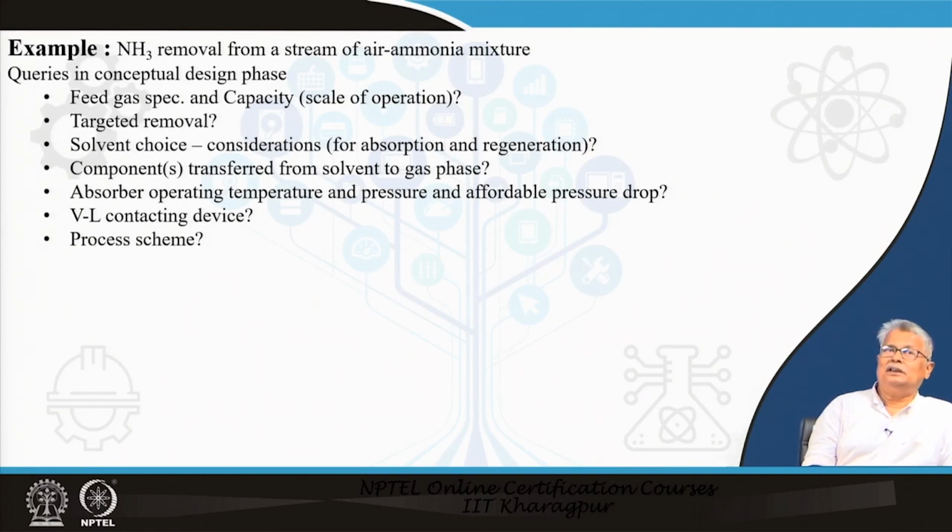There are certain queries in the conceptual design phase. We all know that during our introduction we have said specifically that any process design starts with the conceptual phase. There are certain queries or questions which are asked during this period. The first thing, obviously, what exactly is a feed gas? What is its composition? That is what is meant by specification. The specification would in addition ask for the temperature as well as the pressure of the stream itself.